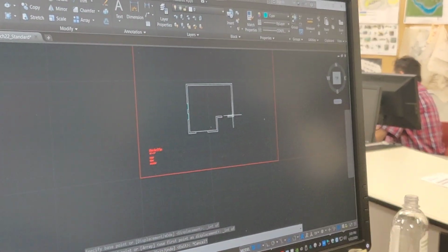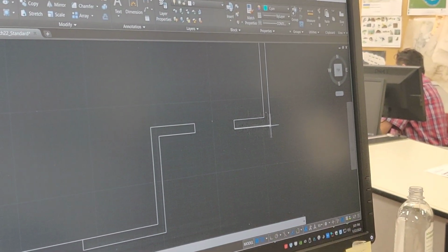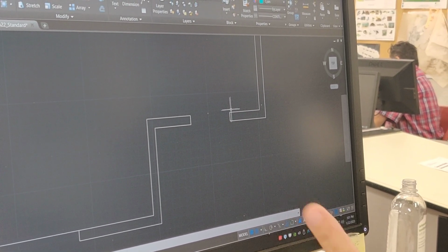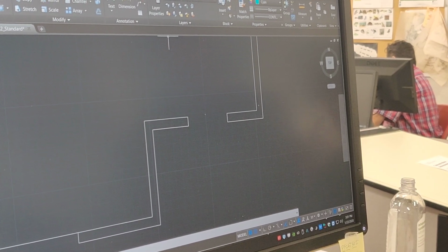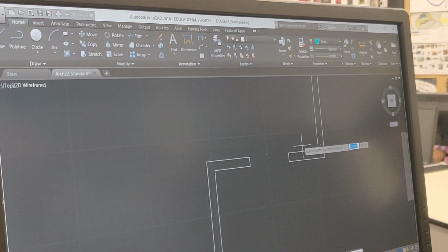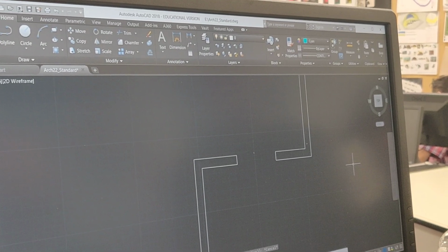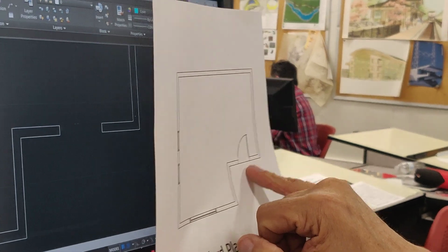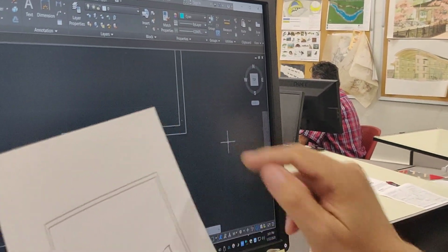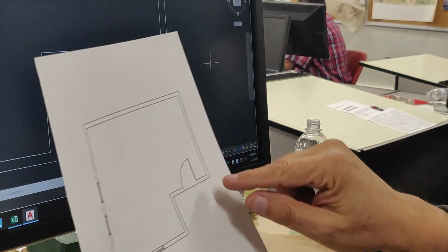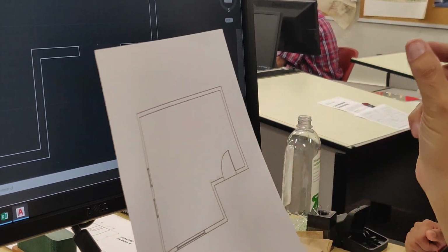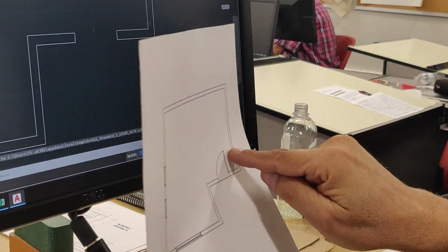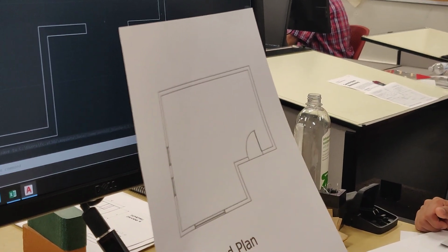Okay, do the same thing for that. For this guy here, you're going to get the door in there, and so you can do a line up there. You get a door swing, circle that door swinging that way, and so oh, by the way, for the door swing, for the door itself, do this line here yellow. So that line across there is going to be the threshold line. Do that yellow. It's not going to be as thick as that. Do the door cyan and leave yourself a little bit of gap for the thickness of the door. And then the arc, we're just showing the arc for that door. Do that in red. Got it?